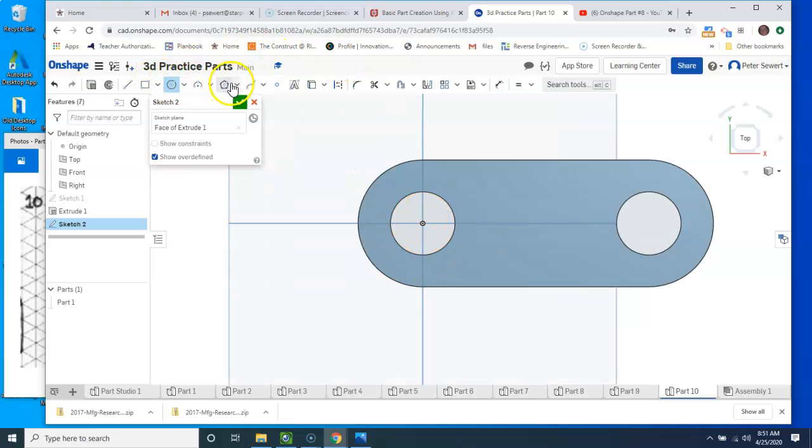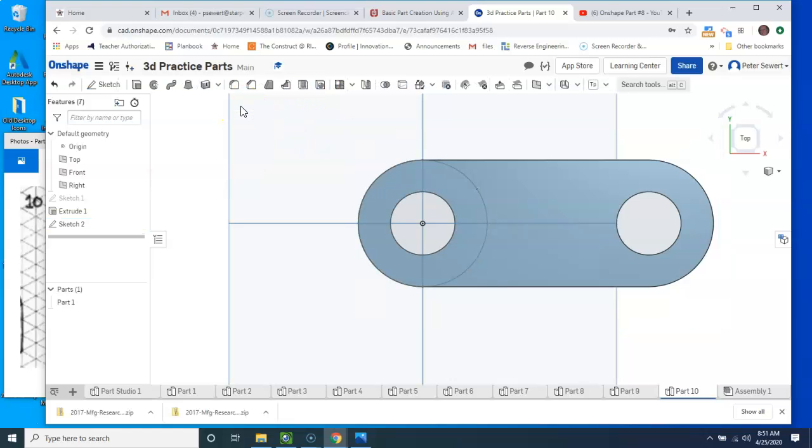And I'm going to use the use tool here. It's to the right of the letter A, because I want to put the diameter of this on the end here. Now I'll start my circle tool, and I'll go from the center here to this edge, and I'll do use again, and I'll get that circle. And I don't have to project that one, or that did project it. I don't have to actually draw it.